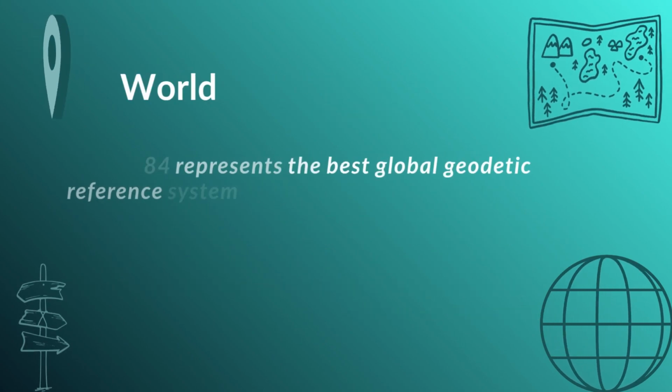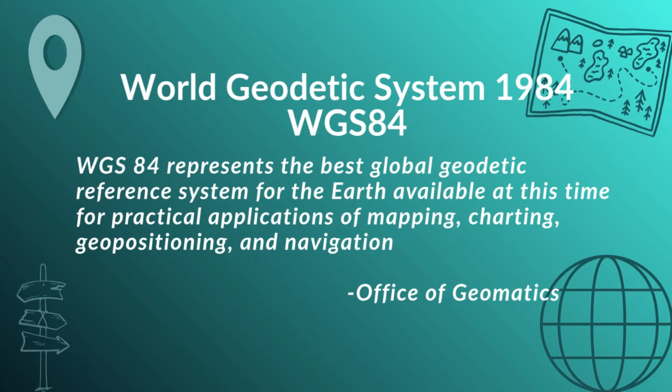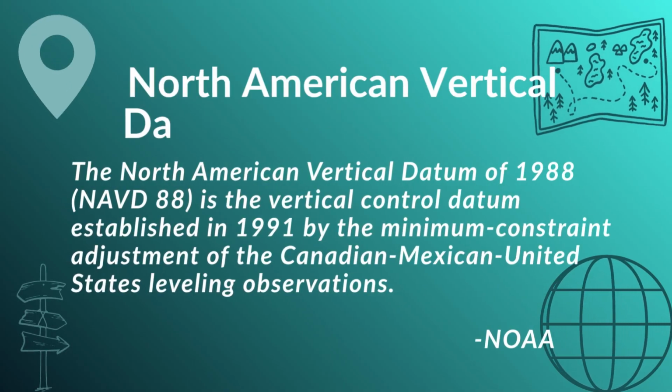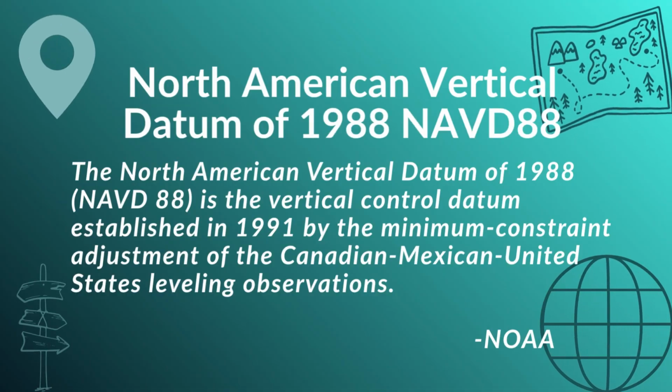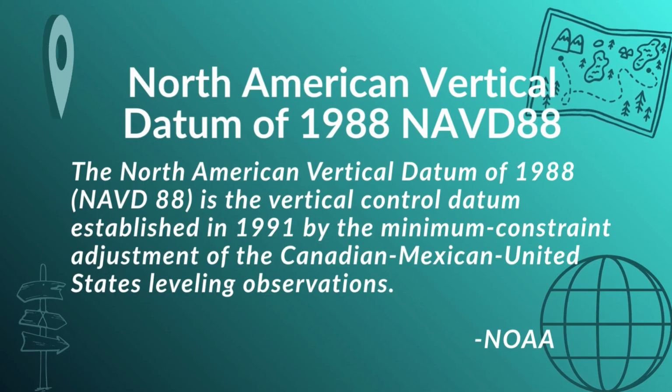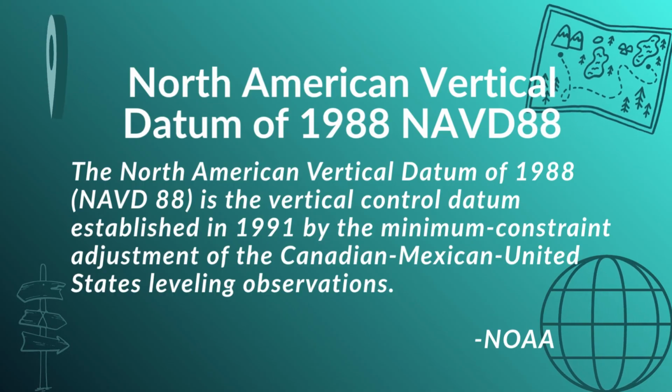We also have vertical datums to contend with, right? To establish where zero elevation physically exists. Yeah, and the critical one for the exam is NAVD-88. The North American vertical datum of 1988. Right, which establishes zero elevation based on a specific tide gauge reading at Father Point in Quebec, Canada.